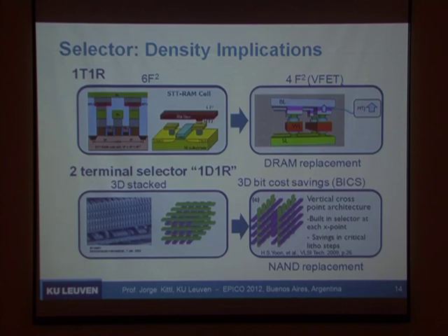And one of the other issues with flash is that NAND flash is going into a 3D scheme. So basically, the stacks that you're making are not as shown here, basically patterning twice to make the cross point, but with one of the arrays flipped vertically, and the main reason to do this is to reduce the number of patterning steps. It's just a cost-saving issue. So again, a lot of physics go into understanding these devices, but at the end of the day, simple solutions like flipping something up, saving huge amount of money in lithography steps may make the difference. When flash did this, it put RRAM in a very difficult situation. You have either an RRAM that can do this or you cannot compete.